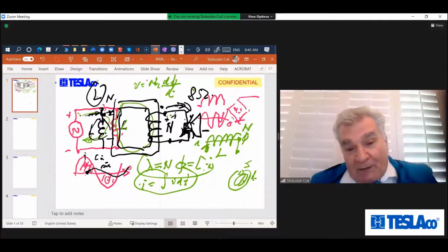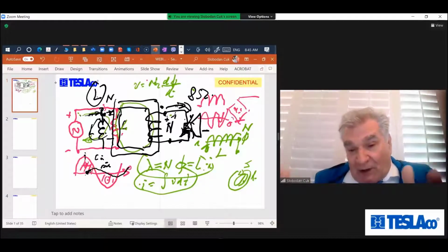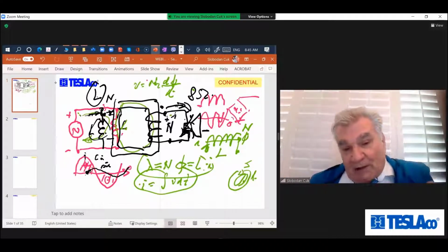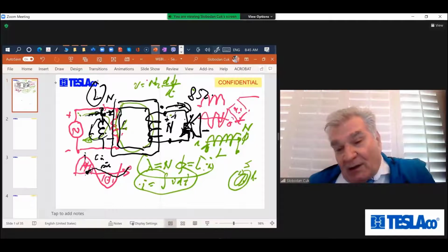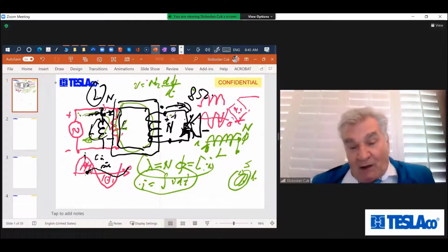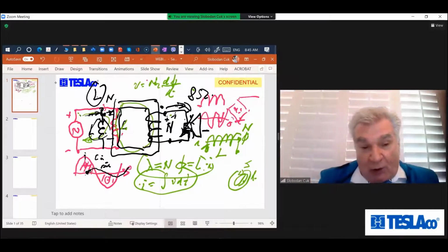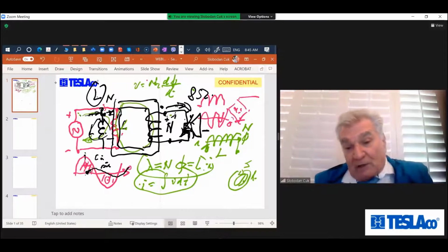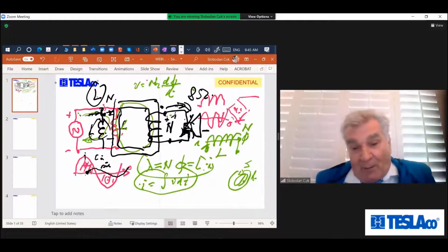But if you want to transfer maximum power from an AC source, music or whatever, to the secondary side, you can derive an equation which will basically say the source impedance has to match the reflected load impedance. That's how you can match this impedance, which you don't have control over: you can use the turns ratio of the transformer and match it for maximum power transfer to the speakers.